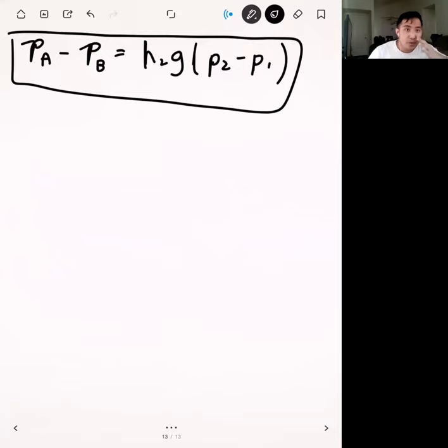So with these manometry problems, the best way to go about them is to do it really systematically, step by step, and then from there you end up with an expression at the end. So draw in as many auxiliary, as many extra points as you need, because I think these problems are easiest to tackle when you're going just vertically and horizontally.